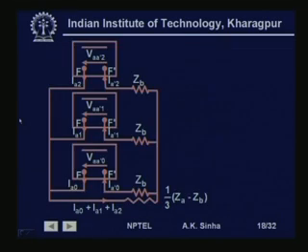So, if we see what current is flowing, I A 1 is flowing through which circuit, then we find this Z B is there, and the circuit that we had seen for the positive sequence network will be there. Similarly, Z 2 will be in series with this Z B and Z 0 in series with this, and of course 1 by 3 Z A minus Z B is in parallel with these.